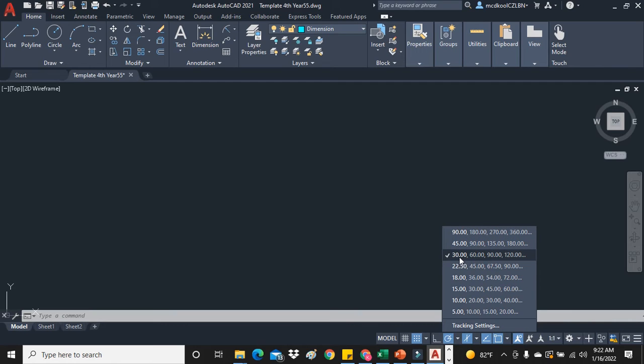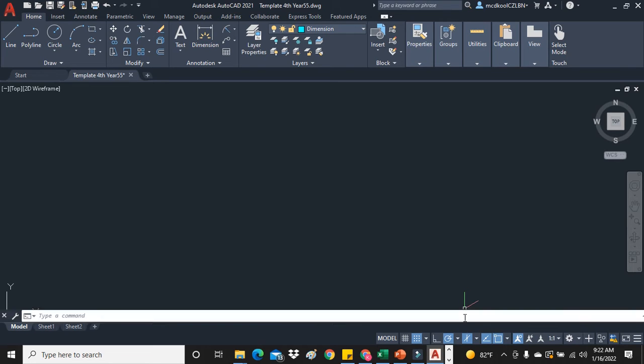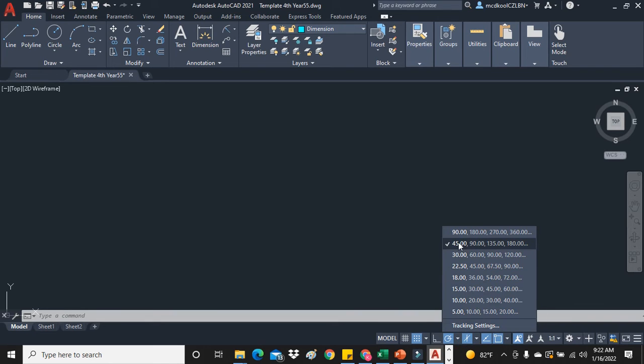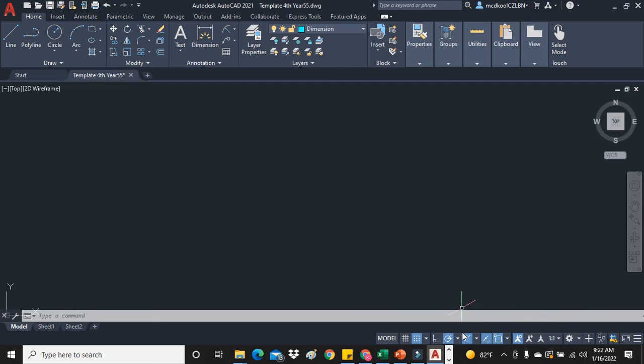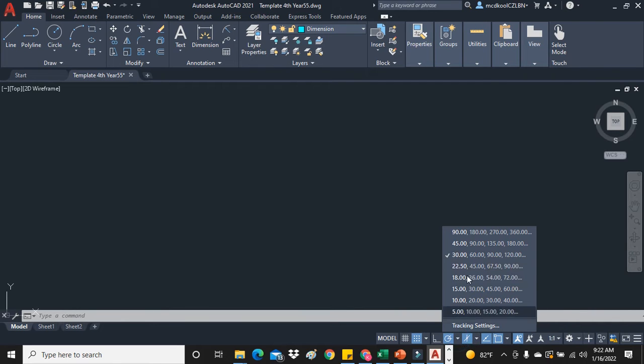For isometric drawings, you will use the 30-60 angle. So it is already selected. If I wanted to select something different, I would just click a different angle, set. So I'm just making sure it's on my 30-60. And then I'm going to go up here to select line.